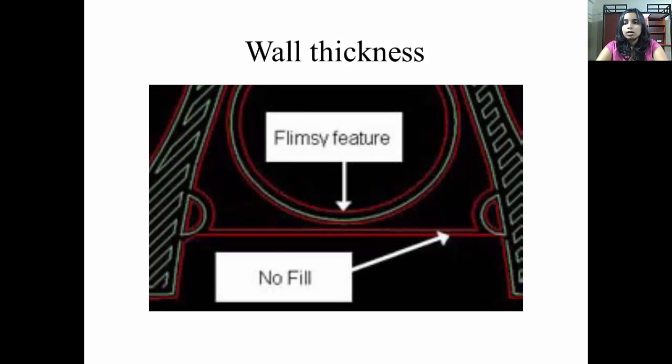So here, in this area which the arrow is pointing towards, the thickness is very small, so we can't calculate the tool path. But in the upper feature we can calculate the tool path, because the area is much wider than this area.